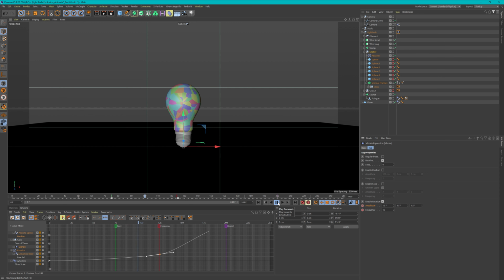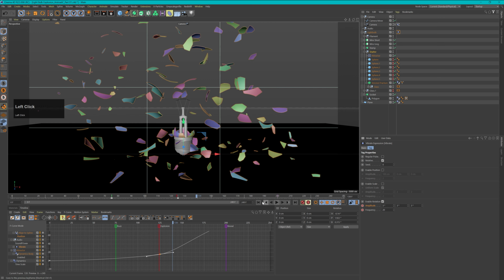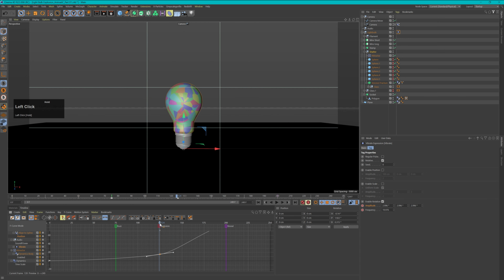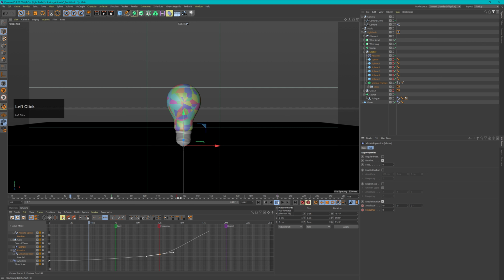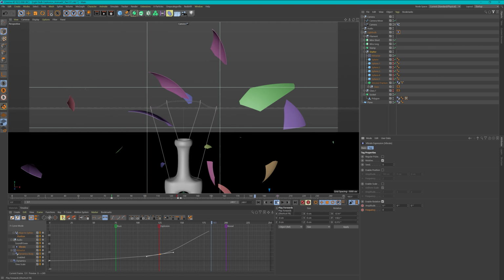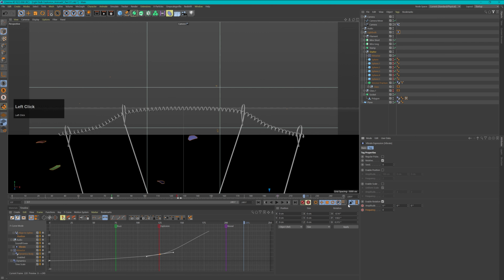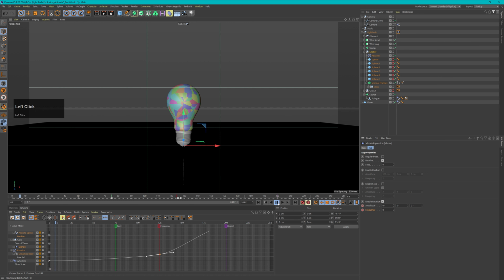Now it starts wiggling. Boom, and then it explodes. And then the wiggling should stop. And we will do this by just animating these back all to 0 within, let's say, 2 frames. Let's set this back to 0, 0, 0, and 0. And let's create 2 more keyframes here. And let's take a look whether this works. And I think that this works quite nicely. Let me turn off my audio and let's take a look at it without audio, because sometimes the audio is a little bit distracting. Wiggles, wiggles, boom, it explodes, the wiggle is off, and everything is in order.